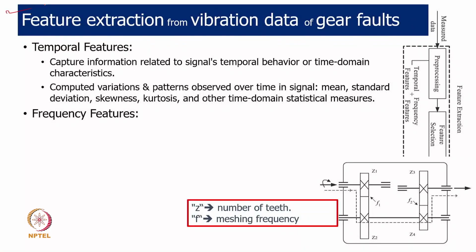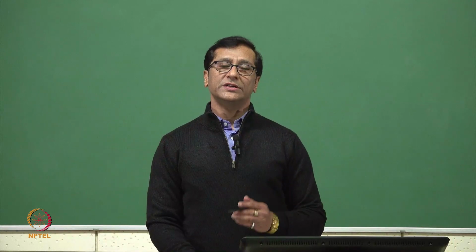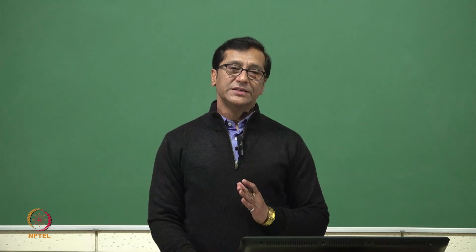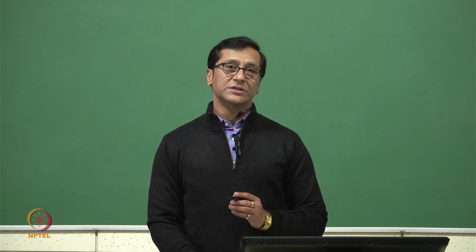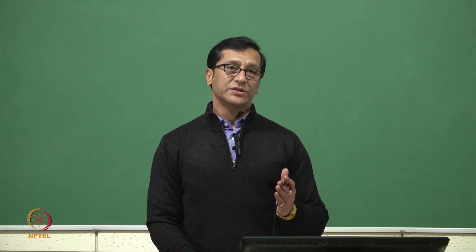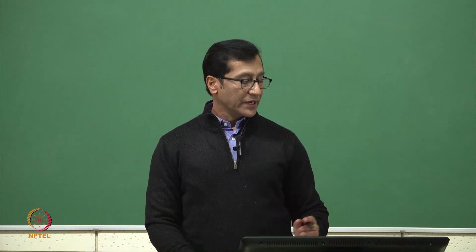So let's take an example of the gear vibration case. We see that this is the gearbox. Here Z1 is the number of teeth, Z2 is the number of teeth, 3, 4. Coming to F1 and F2, they are the mesh frequencies. What is the importance of mesh frequencies? Because mesh frequencies are completely known to us. Whatever the shaft frequency is, the mesh frequency will be related to that. That means before the event itself, we know what kind of mesh frequency we are going to get. If we are getting a signal or a harmonic of those frequencies, how do we analyze and extract the feature will be explained in the next few slides.